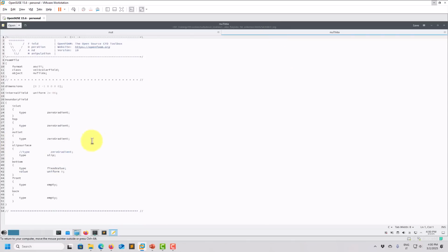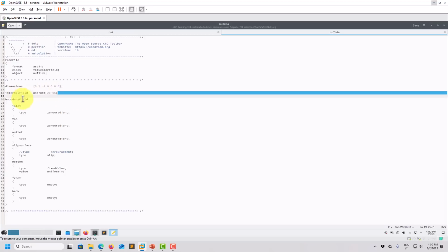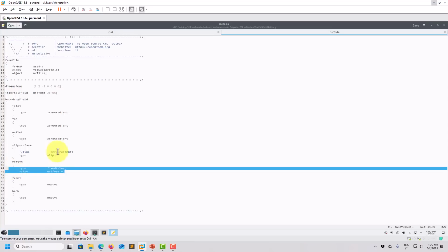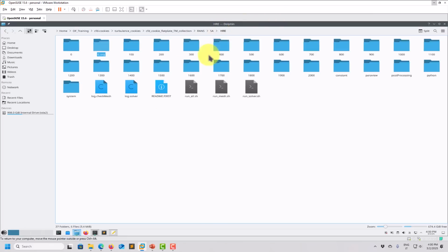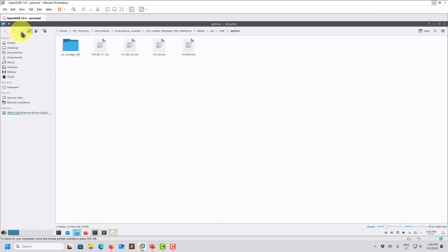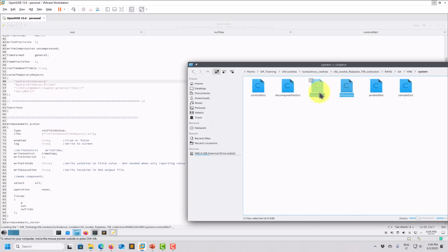Then nu tilde is straightforward, just fixed value 0. Okay, so in this case, I'm choosing nu tilde 10 times the molecular viscosity, then 0 gradient, 0 gradient, 0 gradient, and at the wall fixed value 0. That's all. So as you see, very easy to set up boundary conditions. Now we go to the numerics. Okay, so when it comes to the numerics, pretty much it is the same. We know well these files, I hope, at this point.